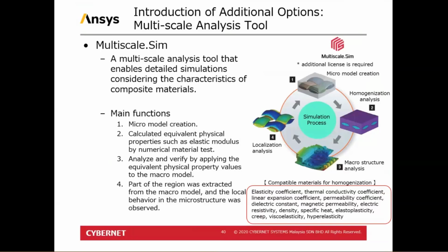Now, it is a multi-scale analysis tool that enables detailed simulation considering the characteristics of composite materials. It is almost similar to the ANSYS Material Designer, but Multi-scale Sim can perform a numerical material test on composites to evaluate macroscopic and isotropic material constants without having to carry out actual physical material testing.